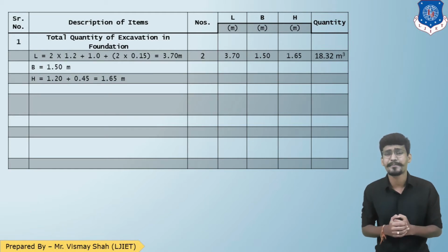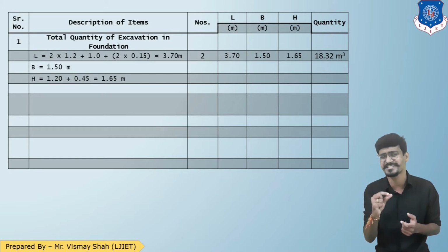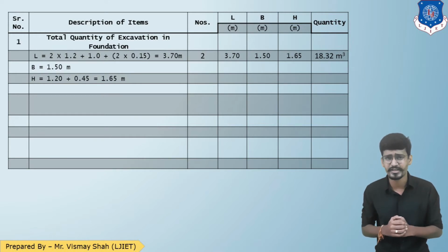The second is cement concrete in foundation. So you always know that for cement concrete in foundation, only the thickness will be changed. L, B and numbers will be the same as for excavation.